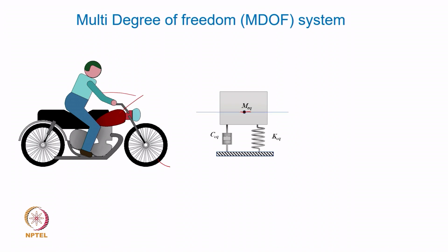That looks okay. We then looked at the vertical motion as the only degree of freedom, as I mentioned to you, and that motion in practice is called a bouncing motion. So, the degree of freedom which we prescribed here, maybe x of t or y of t, is a linear vertical motion, and based on that degree of freedom the governing equations of motion were derived.